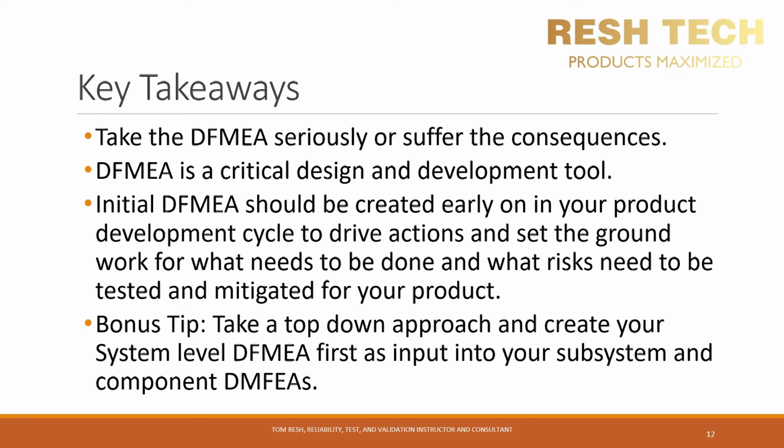I'm feeling really generous today, so here's a bonus tip. Take a top-down approach to the DFMEA process. Start with creating an initial high-level DFMEA for your system that can drive actions and design inputs and trickle down into DFMEA inputs for your subsystem and component DFMEAs.